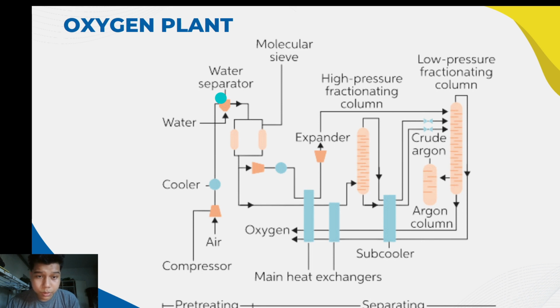The air passes through a molecular sieve adsorber. The adsorber contains zeolite and silica gel-type adsorbents, which trap the carbon dioxide, heavier hydrocarbons, and any remaining traces of water vapor. Periodically, the adsorber is flushed clean to remove the trapped impurities. This usually requires two adsorbers operating in parallel so that one can continue to process the airflow while the other one is flushed.